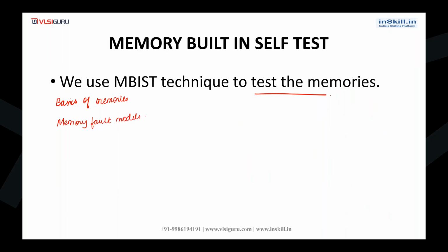There are various fault models like stuck-at, transition fault, address decoder fault, coupling fault. We will understand about them.